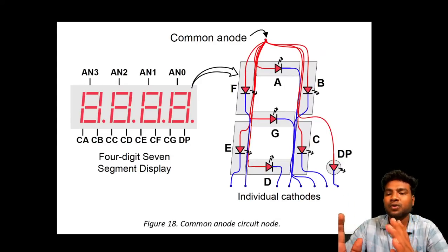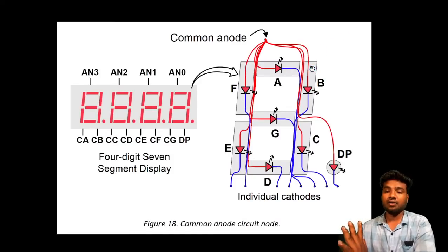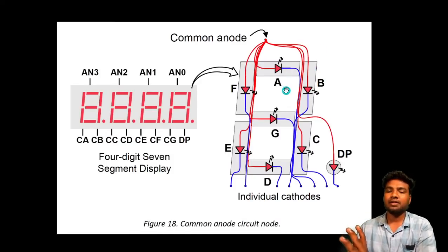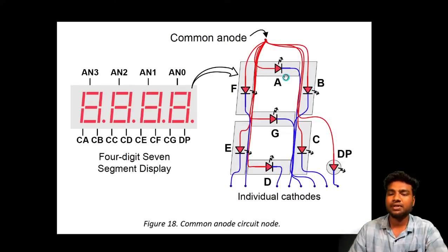The first LSB bit is for A, the first LED, and the second LSB bit is for B, the second LED. We have to count from the LSB side. So the first binary is for A, the second for B, the third for C, then fourth, fifth, sixth, and so on. A B C comes from LSB to MSB.